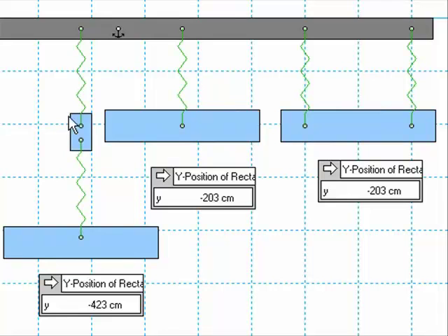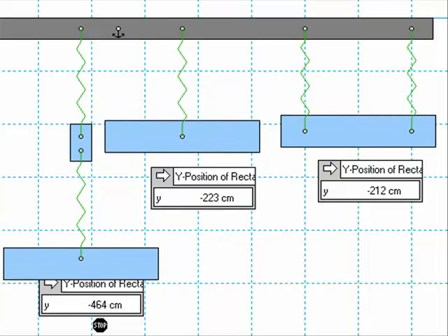The one on the left, these two springs are on top of each other. So with this one here stretching 20 centimeters, each of these should stretch 20 centimeters, so there should be a total being read of 40 centimeters. By the way, this little connection piece here I made virtually massless, very little mass compared to this one. So this one here should stretch by 40 centimeters. And when you look at the number, indeed, that's what you can see. So each one of them stretches by 20 centimeters, which is the original amount of this one, and that's pretty much what I said in the problem that I calculated.